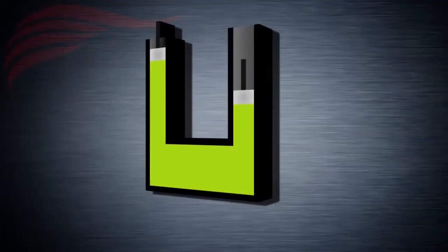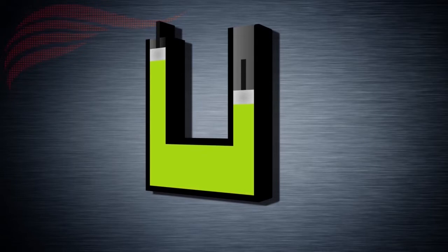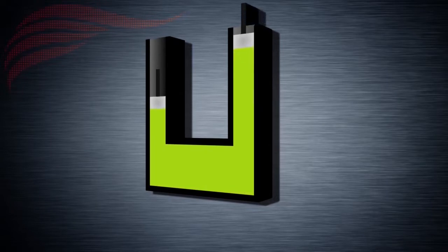To illustrate this, let's look at a container with two pistons of equal size. This is the simplest type of hydraulic system possible. If a force is exerted on the first piston, it will apply pressure on the fluid, which will be transmitted through to the second piston. Because the two pistons have the same surface area, the force exerted by the second piston will be exactly the same as the force that we applied to the first piston.